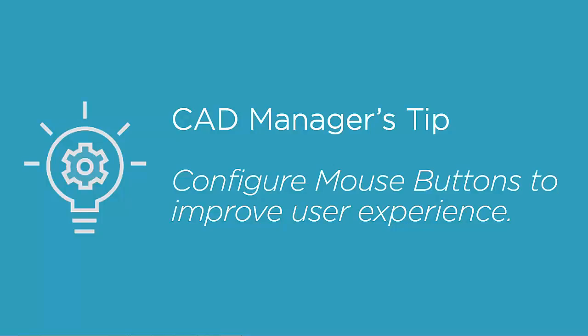In this CAD Manager's tip, I want to go over how to configure the mouse buttons before moving on to the next section. Now, you might be asking yourself, why do I need to change the mouse buttons? Let me just say that out of the box, the default button setup isn't like other CAD programs, so let me explain the differences and how to change it. The main difference is how the middle button is set up. By default, the middle wheel is only set up for zooming in and out by scrolling the wheel back and forth. Pretty standard. Now, if you want to use the middle wheel as a button for snapping like AutoCAD, you won't be able to unless you do the following.